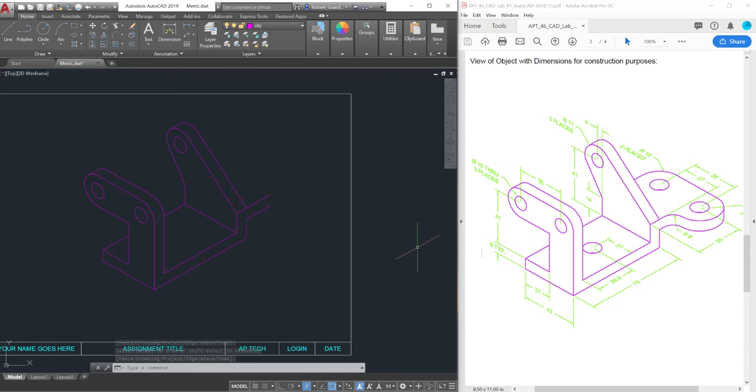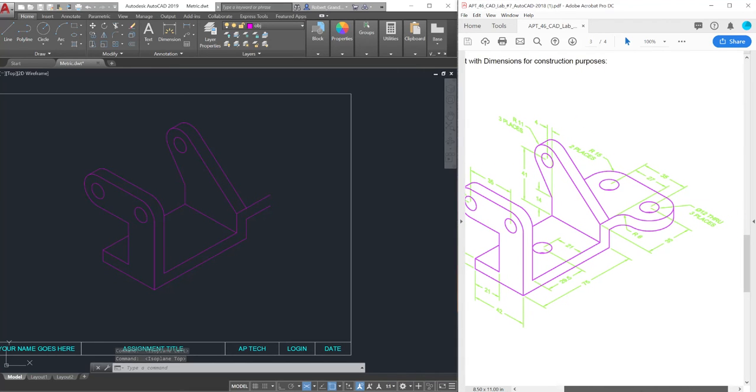This area here is what gives people the most problem. It's really not too much different from what we did here. So again, what I'm going to do is draw an ellipse in the wrong location and move it. It's the easiest way to do this, I think. So I'm going to switch to my top plane. I'm in my top plane view now. And we can see that these objects in this view have a diameter of 12 in 3 places.